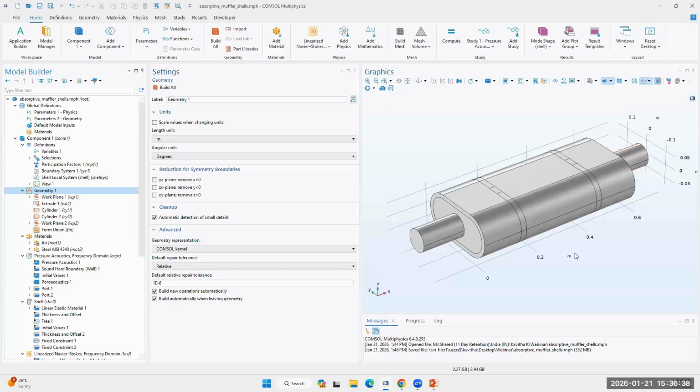In real muffler systems, the main effect of acoustic structure interaction is probably due to the elastic vibration sources that arise from the vibrations in the full exhaust system. In this particular model, the vibrations are induced only by the pressure waves in the air inside the muffler.